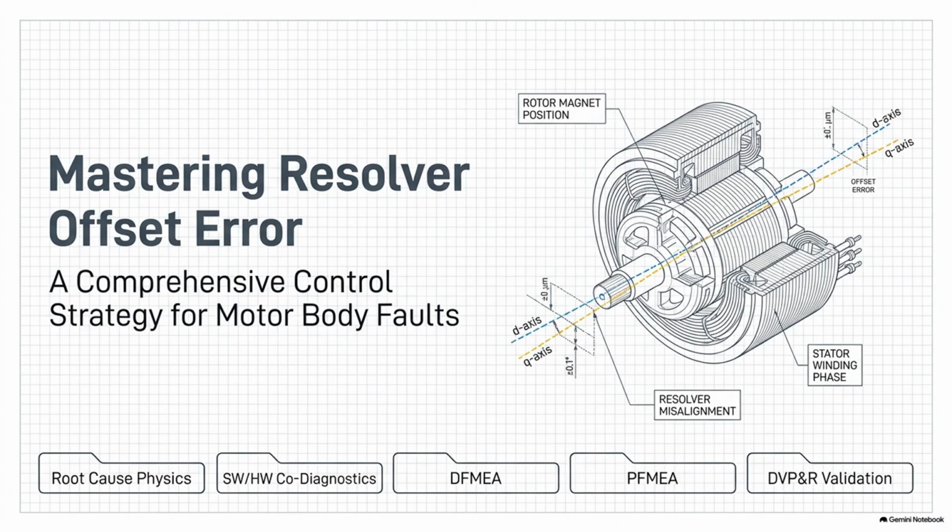Exactly. ASIL D, for those who don't spend their days reading ISO 26262 functional safety standards. That is most people, I assume. Right. Well, ASIL D is the highest, most stringent level of safety classification. It means a failure here poses an immediate life-threatening risk to the occupants. So things like steering, braking, and unexpected motor torque, those are all ASIL D.